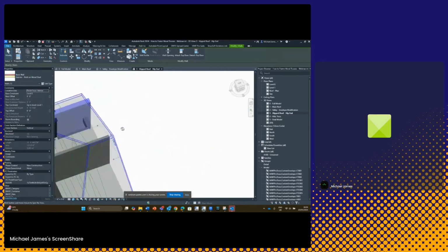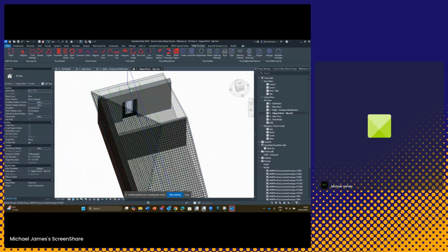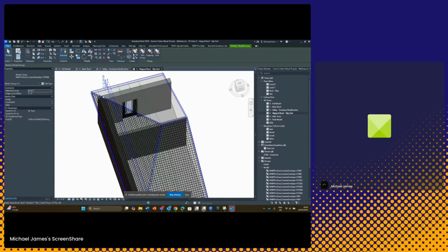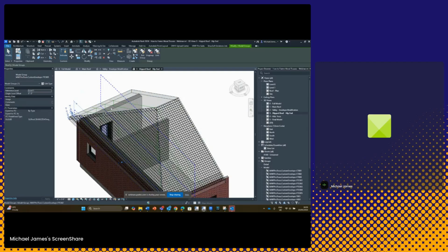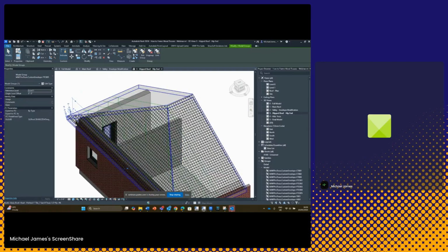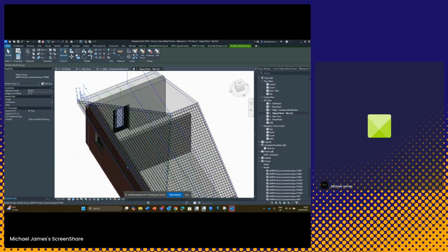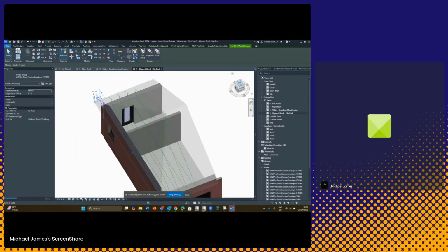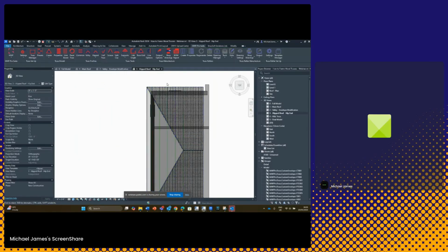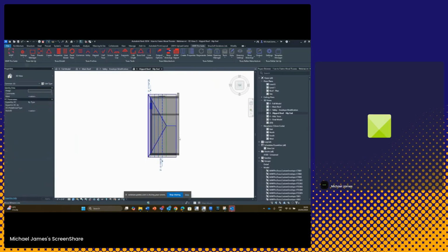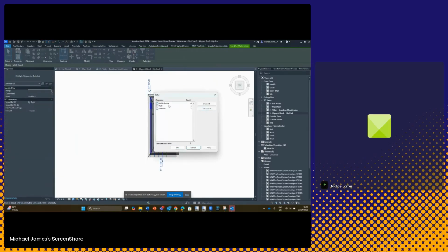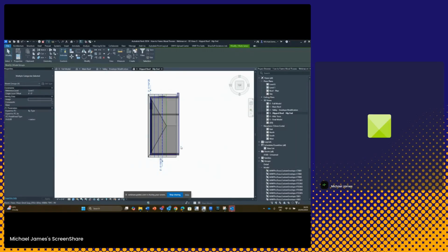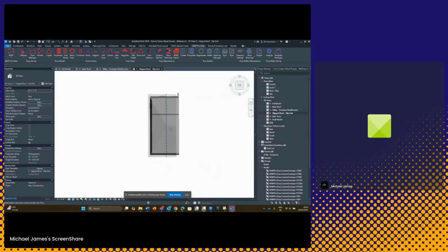And we can see we've got multiple hip girders generated in these areas. So the minimum height would affect how small the hip girder can be when it gets to the edge of this part of the roof. I am only going to define one at the hip intersection. So technically I don't need these ones. That was just to demonstrate that we can create multiple if necessary. Okay. So I'm just going to select these model groups and simply delete them. Okay.